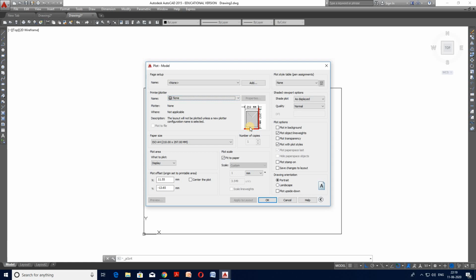If you want to convert this drawing file to the PDF, you can convert this. So for that you have to select the option DWG to PDF converter. So this is what DWG to PDF converter. Click it, and then again below this there is a paper size option over here. So you just click it.